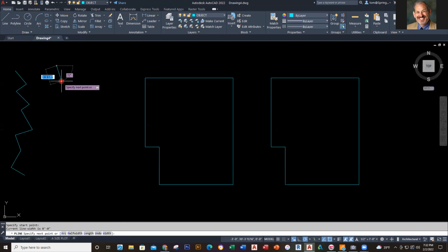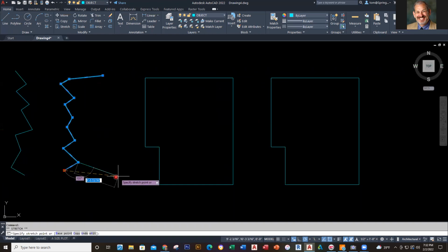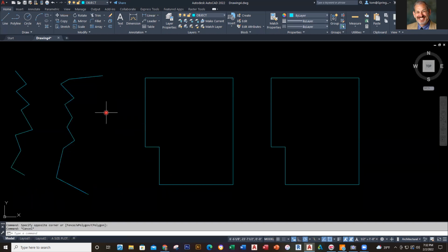When I use the polyline and I use my zigzag, I go ahead and go like this, bring this down like this. All right, and I click on this, and all that's connected. So the beautiful thing on a polyline is you can actually move the edges around like this, and you can click on these middle bars and pull the whole line aside. So that's the difference between a polyline and a regular line.